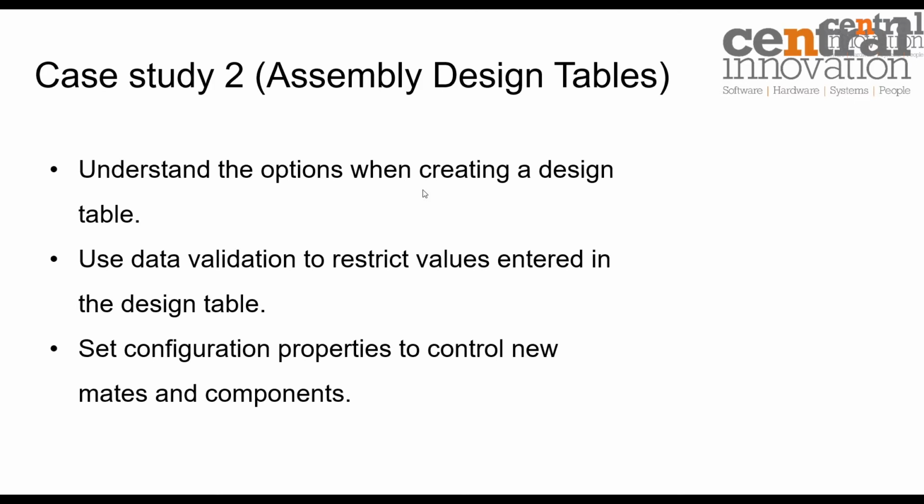I'm going to show you how we can create a design table inside an assembly, and then I will use some functionality of Microsoft Excel named data validation to restrict some values entered in the design table. And I will set some configuration properties to control new mates and components inside the design table. So let's move forward and we can see how it can be applied inside an assembly.